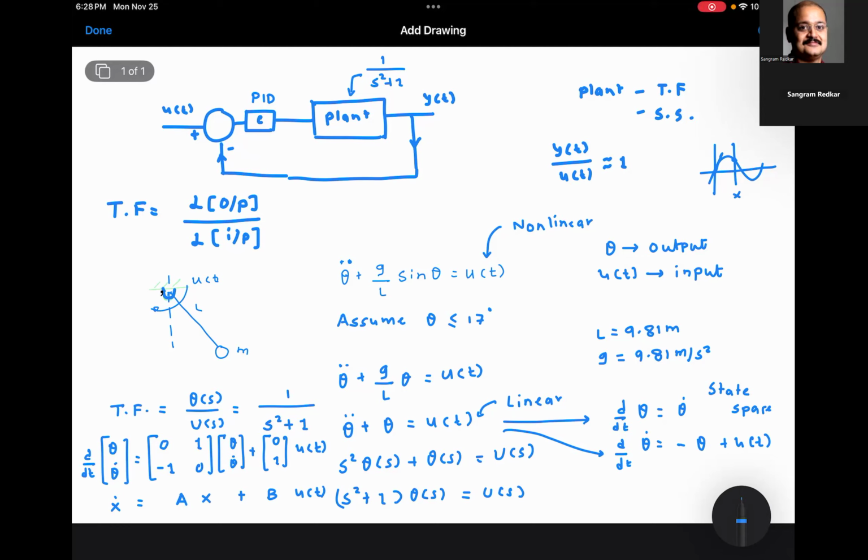Next, simple PID has its own limitations. So there is something called the 2 degree of freedom PID, which adds weight on the set point and the disturbance rejection. Many times, simple PID does not work. Rather than going to some complicated method, try 2 degree of freedom PID. This simple weighting technique most of the time would work.